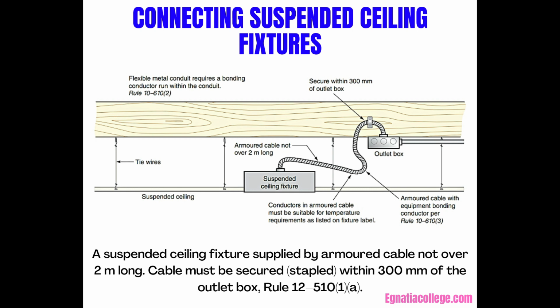Rule 12-1010-3 specifies that when flexibility is required, flexible metal conduit does not require a clip within 300 mm of the outlet box except where the metal conduit is fished, and no lengths over 900 mm at terminals where flexibility is necessary. Or armored cable containing conductors suitable for the temperature requirements as stated on the fixture label, usually 90 degrees Celsius. Be sure to staple the armored cable within 300 mm of the outlet box.